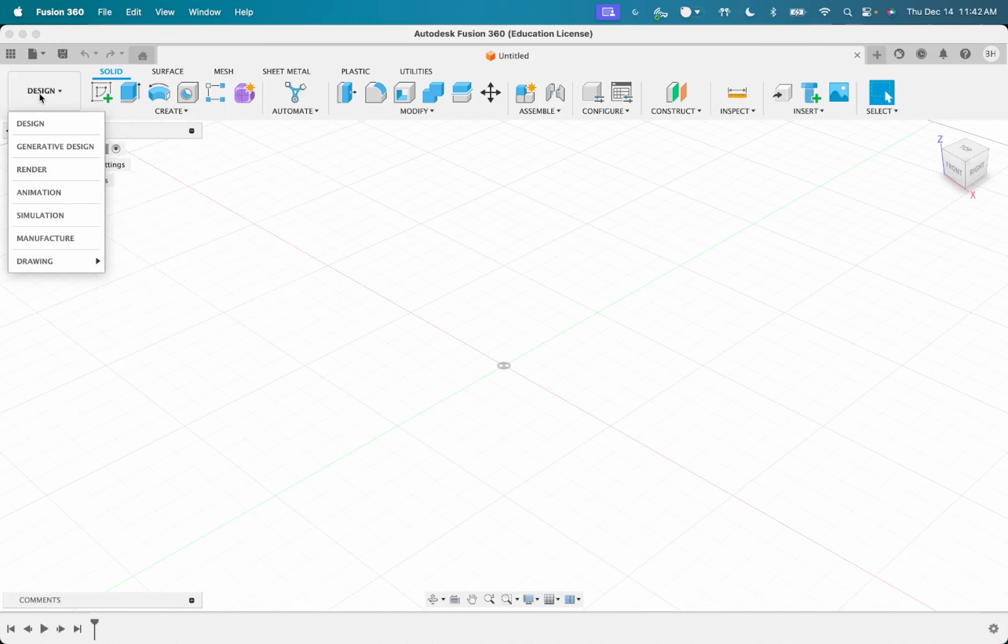But for our case today in the Fusion 360 modeling course, we're just going to focus on staying within the design workspace. If we take a look at our design workspace, we have our toolbar at the top, a view cube in the top right, motion controls here, and comments, and we have this thing here that doesn't have anything in it yet, but we'll talk about it later. Then you also have your browser right here, which gives the structure of the file.